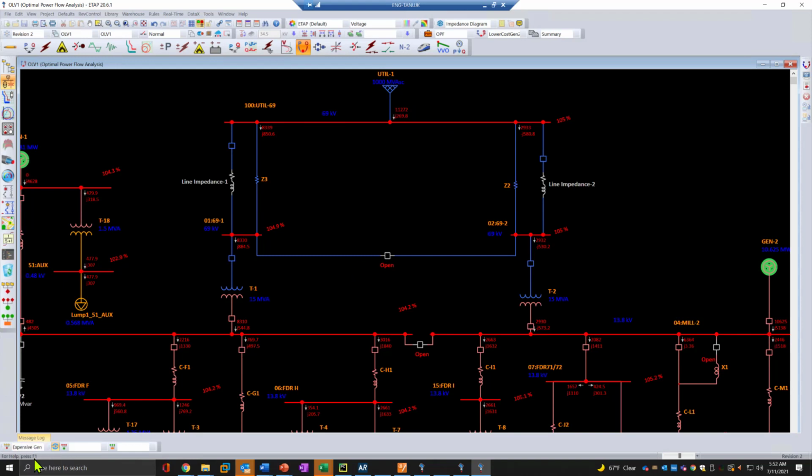And finally, when we have our generators expensive, both generators are expensive. So in both cases, the real power essentially goes to 0 megawatt, and we are using them again purely for the reactive power. And maximum power, almost 22 megawatts, is now actually coming from the grid. So this could be a case where we have switched the fuel on the generator, and the cheapest source based on the energy price and the loading of the system happens to be the grid. Now these are all snapshots in time, and when we look at the operate side, we can see how this dispatch works on a continuous basis.